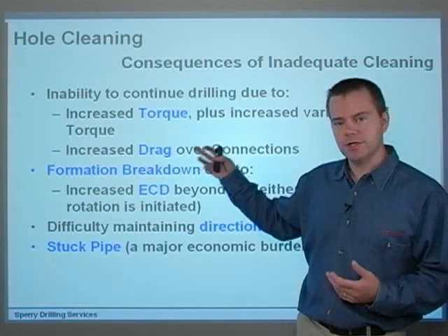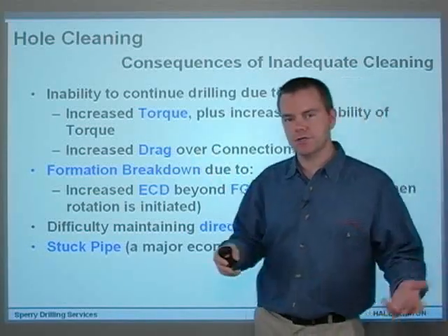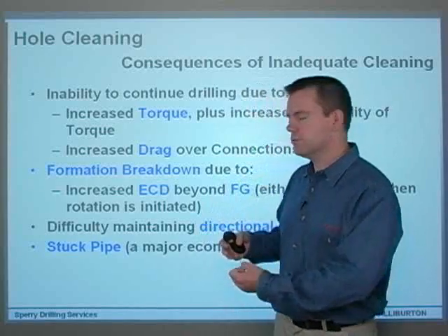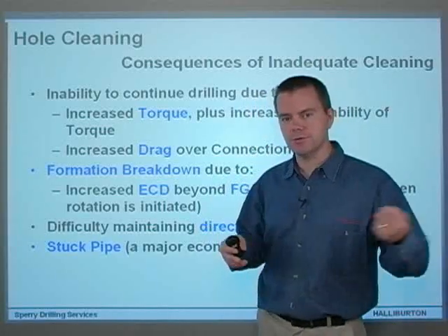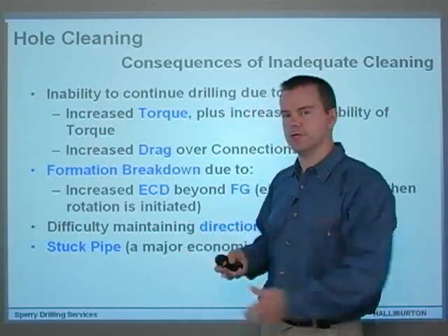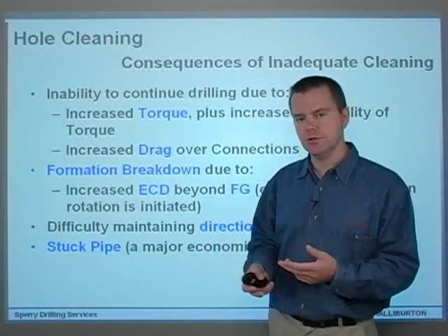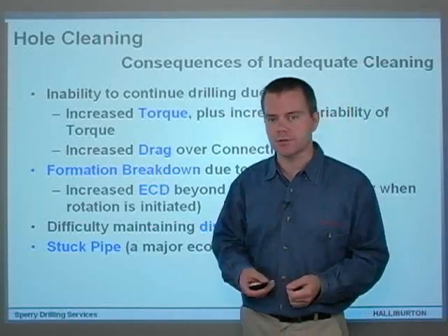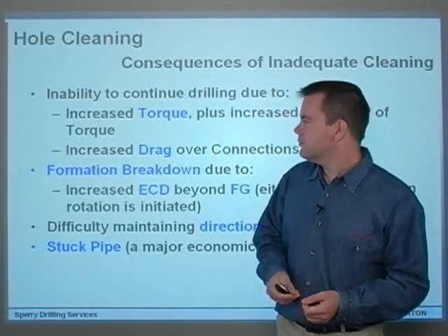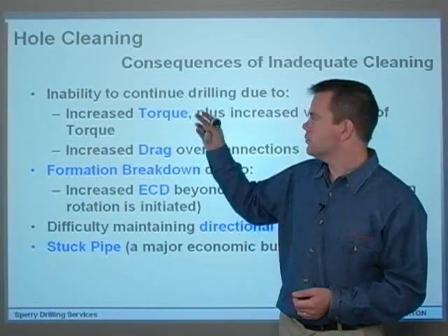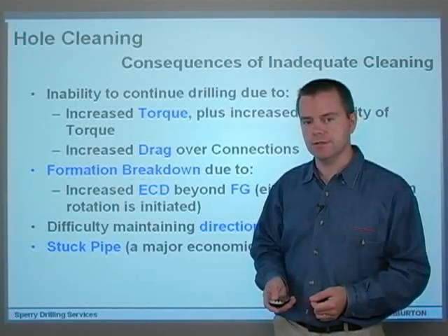You'll end up with an increased drag on connections, and increased drag on trips and so on. So it's going to be far harder to pull out of the wellbore, and also quite difficult to get back in with new BHAs, also casing and so on. So if you don't attend to it, you won't be able to drill the entire well to TD.